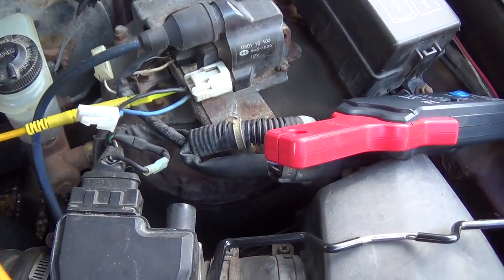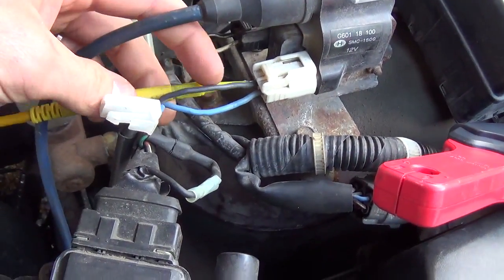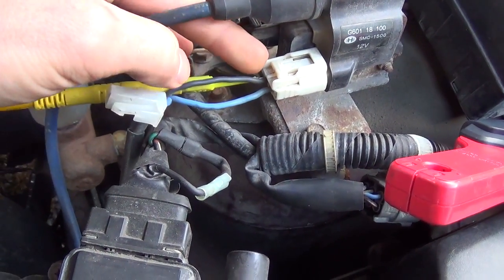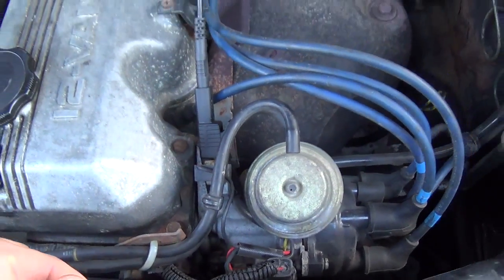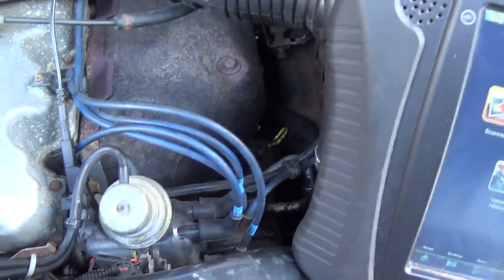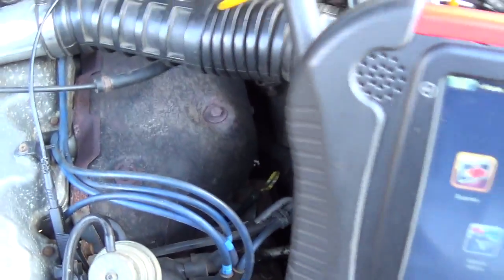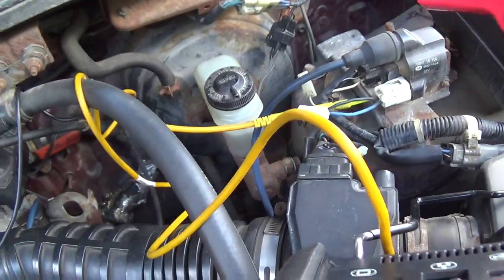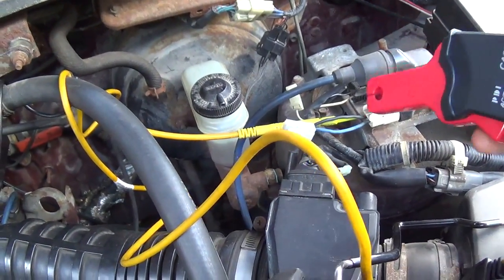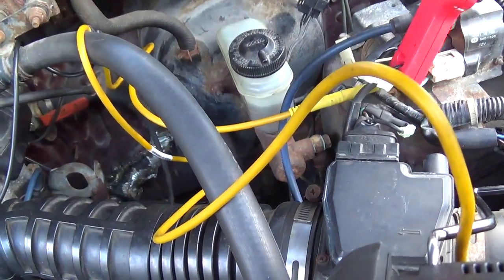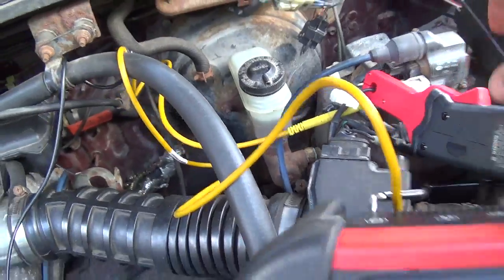Channel 1 is going to be our voltage drop. So there's the lead back probing the wire there, and my ground is on the distributor body since we're interested in the voltage drop basically across the ICM. So that's the easiest place to connect it. And then our current clamp, let's turn it on, re-zero it, is going to measure current this way on that black wire.